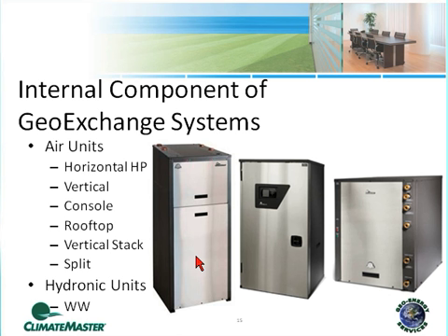We'll bank 3 or 4 or 5 of these units together and then stage the compressors. So we basically create an 8-stage or 10-stage boiler or chiller configuration to supply hot water or chilled water to coils that may be mounted in your traditional air handlers.